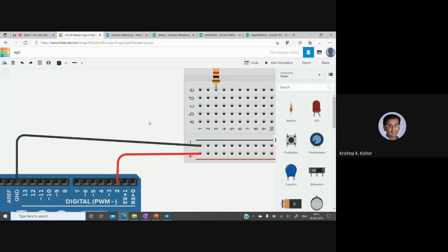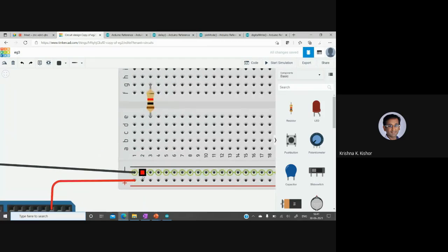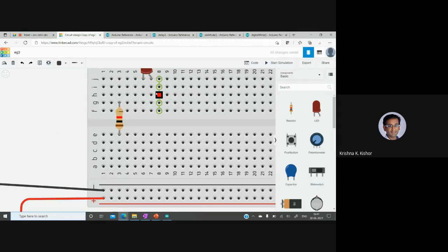Then what happens? So now I've connected to the board. So this line is completely black, which is ground, and this line is completely the reference 5 volts. Now I want to connect this to the LED anode. So I want to draw a line all the way from here to here, and I'm going to give it a separate color. All internal connections we can give a separate color. I'm going to give it a green color. So the current goes from the board, to this line, goes from here, all the way through this wire, goes to the anode, and comes out through this cathode part.